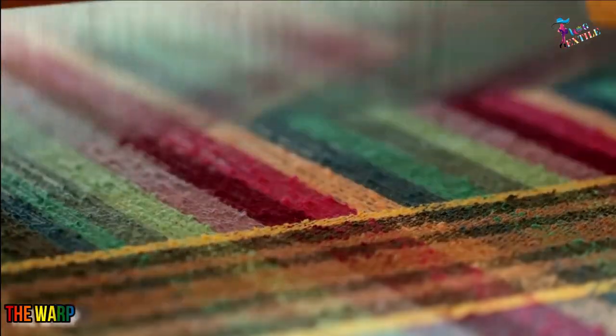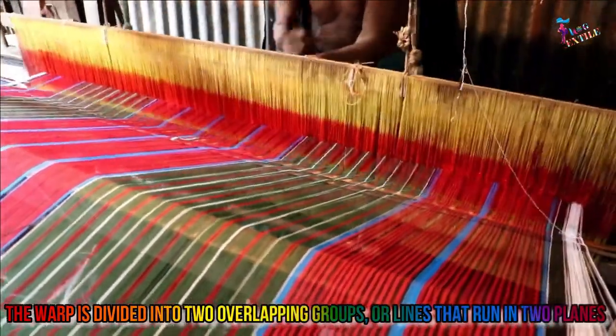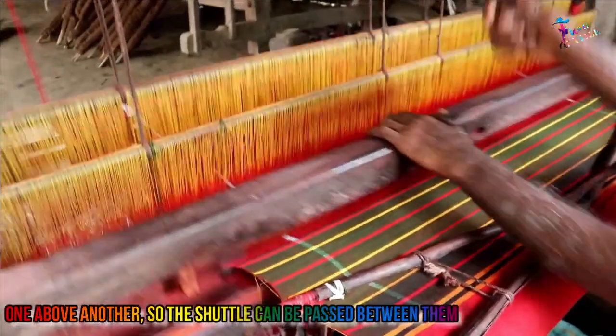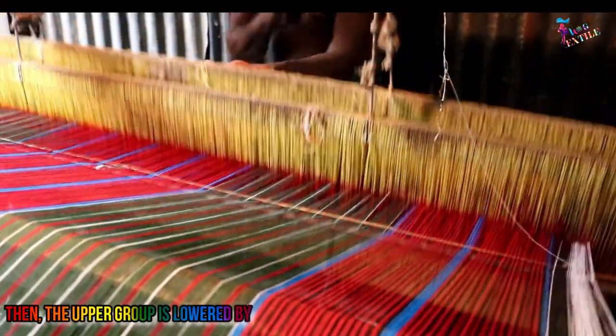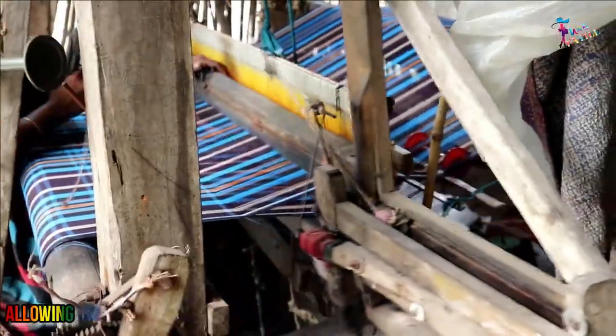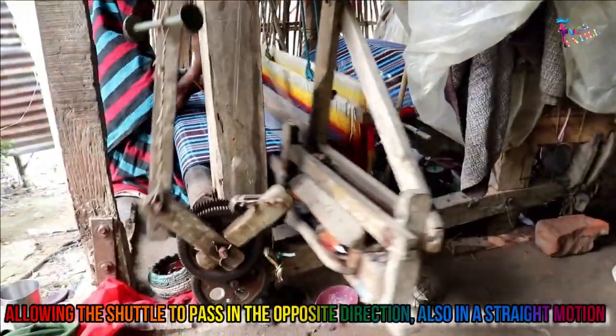The warp is divided into two overlapping groups or lines that run in planes, one above another, so the shuttle can be passed between them in a straight motion. Then the upper group is lowered by the loom mechanism, and the lower group is raised, allowing the shuttle to pass in the opposite direction, also in a straight motion.